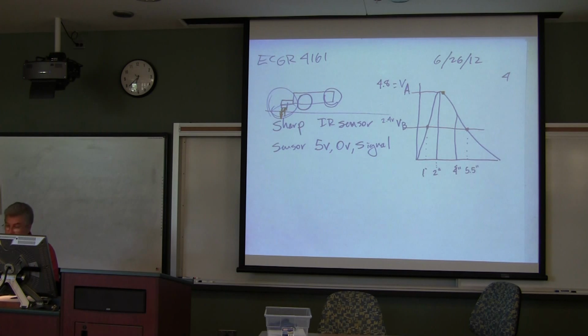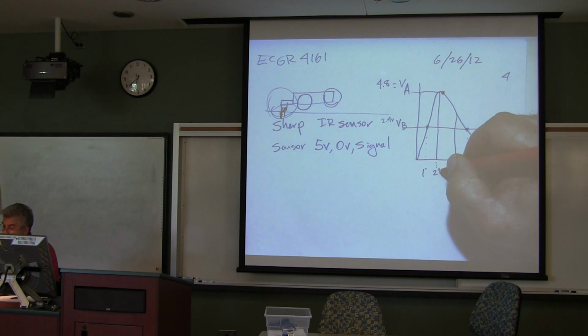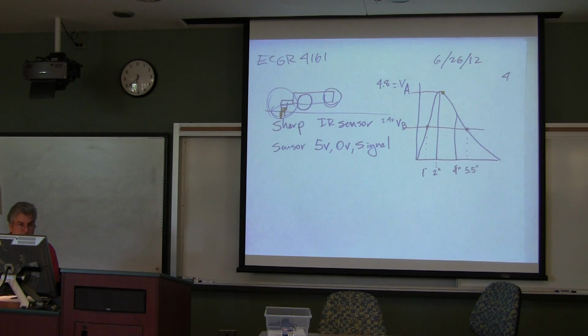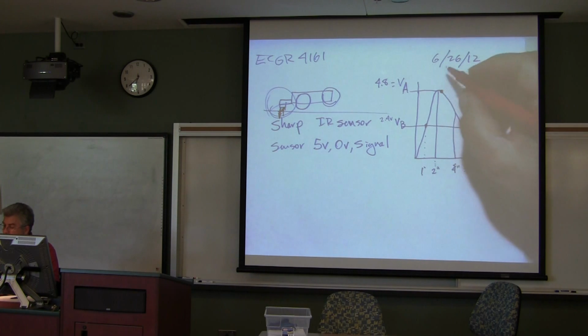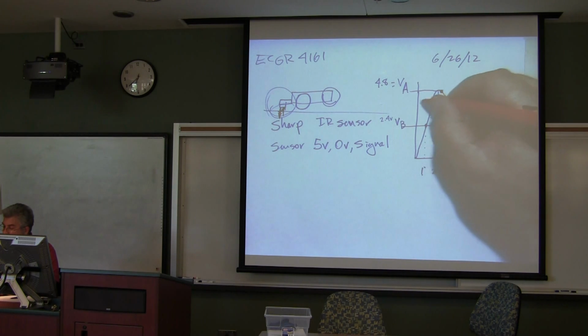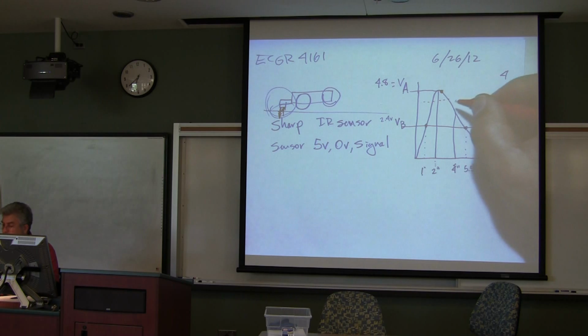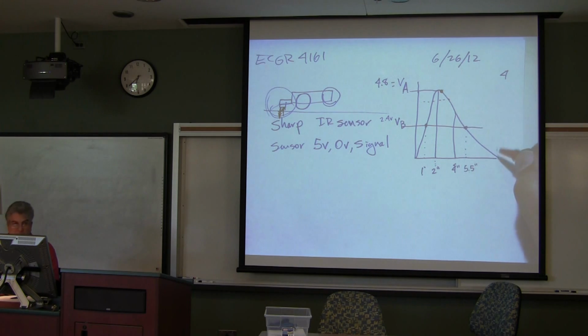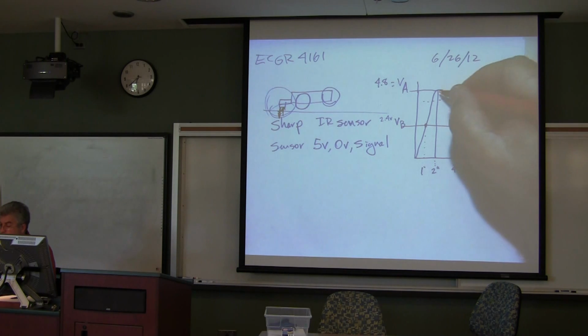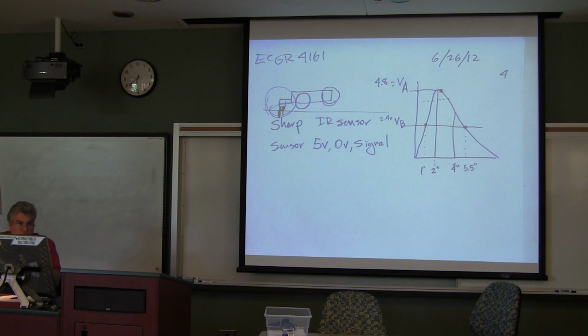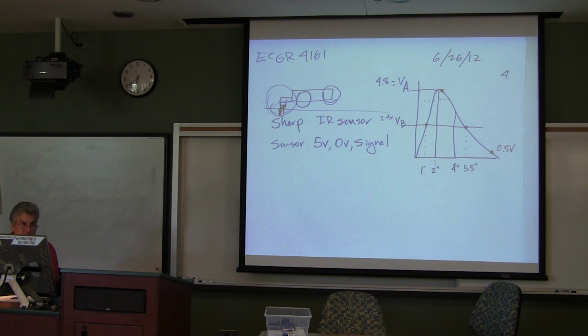So you would say, I'm going to mount that sensor 2 inches above the floor, and anytime I get a voltage at some threshold and below, that means that something's going wrong and I better watch out. Especially if you go from measuring 4.8, 4.8, 4.8, 4.8, whoa, 0.5 volts. What will that tell you? You hit a cliff, right?